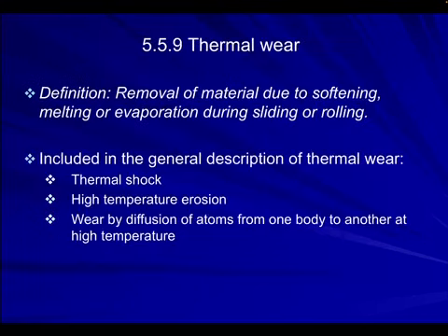Then thermal wear is the removal of material due to softening, melting, or evaporation during sliding or rolling. So this is where you've got maybe thermal shock or high temperature erosion and wear by diffusion of atoms from one body to another at high temperature. So remember, at high temperatures you get a lot of other mechanisms that also take place.